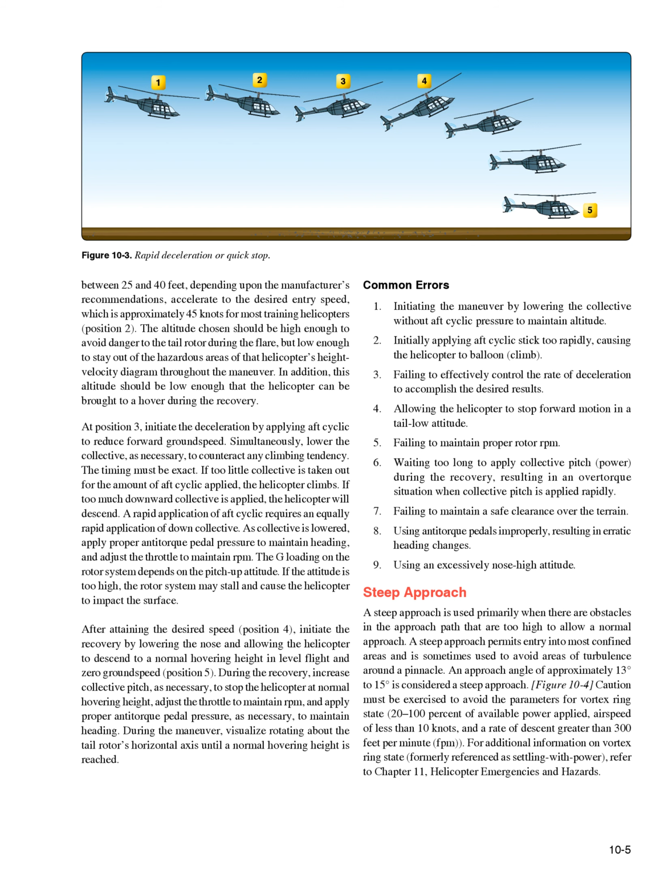6. Waiting too long to apply collective pitch, power during the recovery, resulting in an over-torque situation when collective pitch is applied rapidly. 7. Failing to maintain a safe clearance over the terrain. 8. Using anti-torque pedals improperly, resulting in erratic heading changes. 9. Using an excessively nose-high attitude.